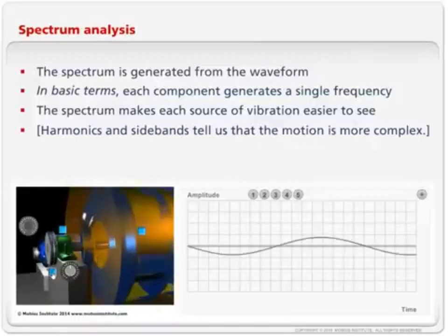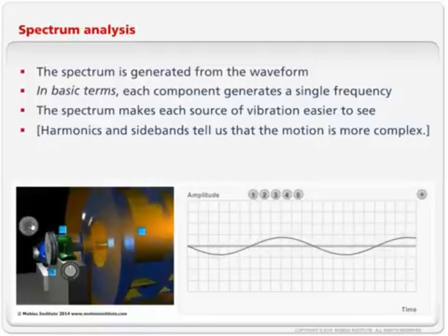Imagine, if you will, that motion you can see there in the animation from the shaft turning. Just for the sake of this demonstration, you can even see the shaft is bent. Once per revolution it makes that cyclic motion. It would make a similar motion if it was out of balance as well. So there's our little simple sine wave, and we can speed up the machine a bit, make it a bit more interesting sine wave.